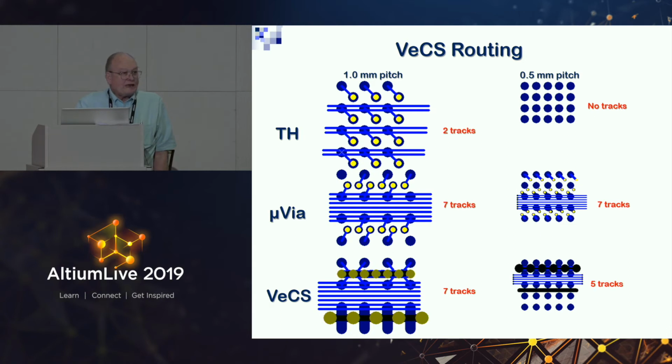So it's not exactly as high density as HDI, but it's enormously lower in cost because the fabricator doesn't have to buy the very expensive laser and doesn't have to deal with the problems of plating a blind via, which is very difficult. So it's much lower in cost when you actually buy the PC board. But again, it's not a multi-layer. It's a whole different strategy in terms of how you do your wiring.